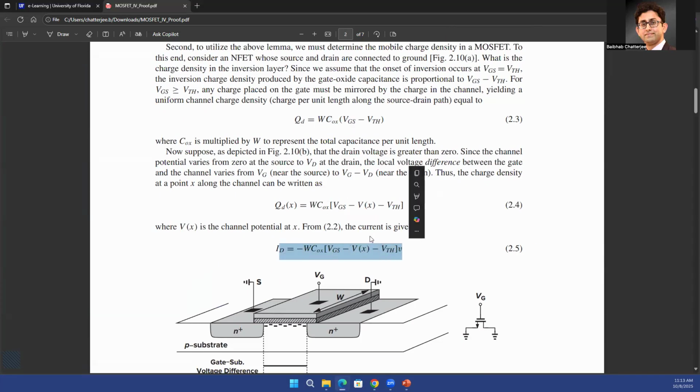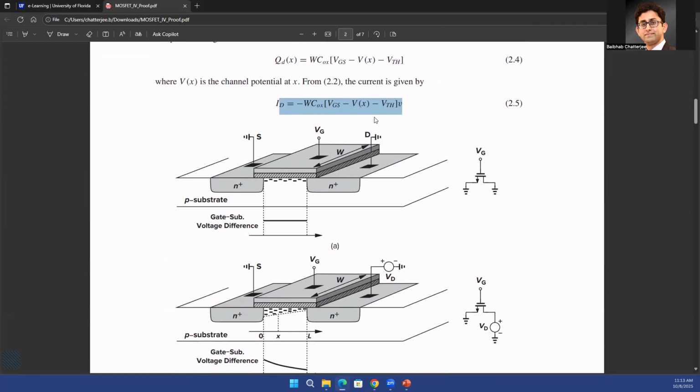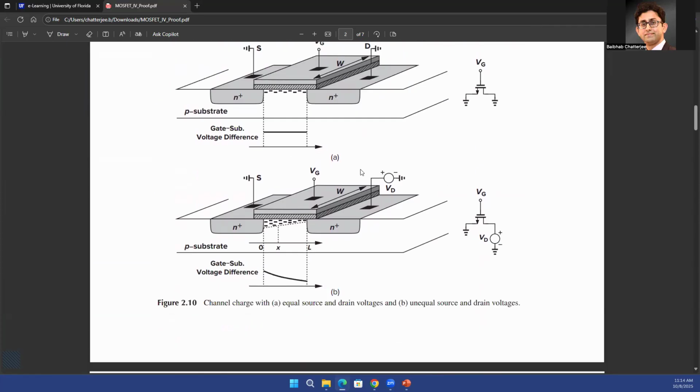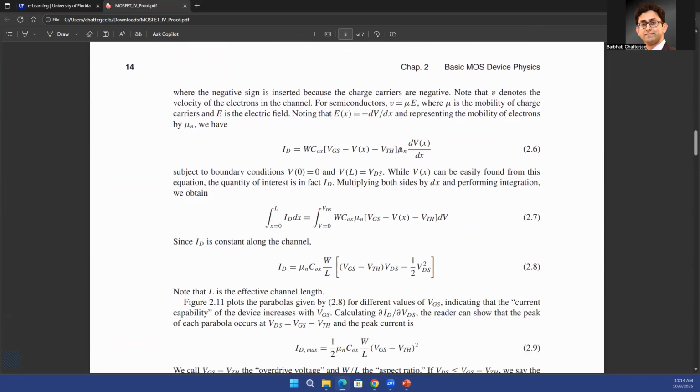It's the threshold voltage. And then you represent your ID current as a multiplication of velocity along with that charge. And then you represent your velocity as mu times dV dx. Now, this is the difference with the PowerPoint slides. In the slides, instead of assuming your electric field as minus dV dx, we just assume dV as VDS and dx as L. So that was an approximation, right? You know that the derivative only works if it is a small change in the quantities.